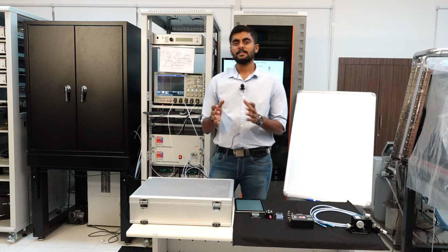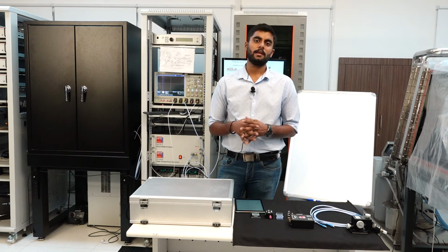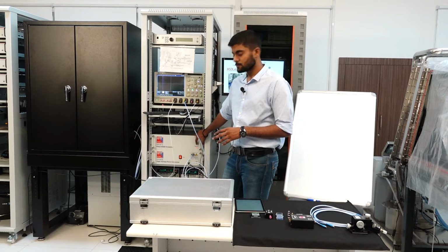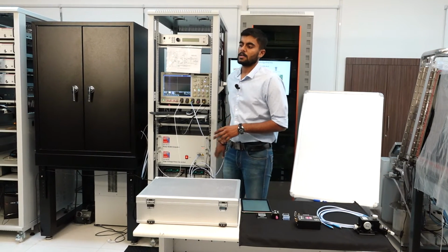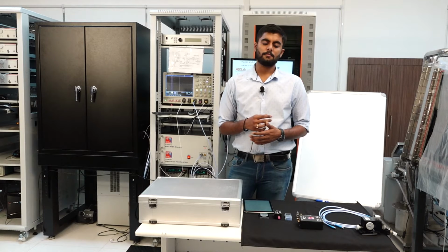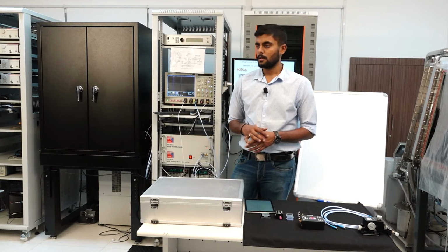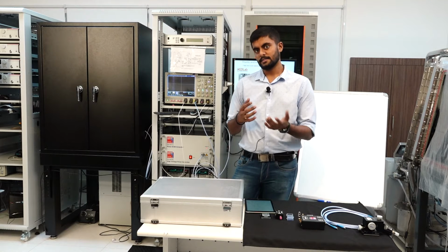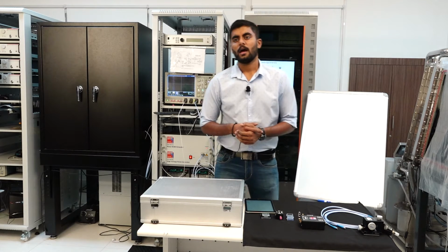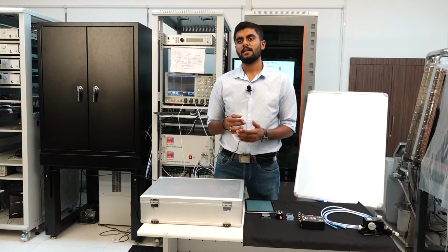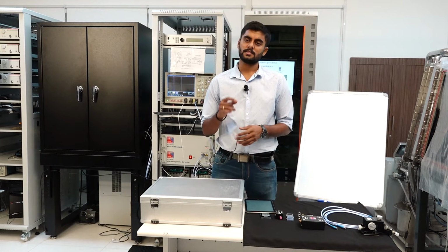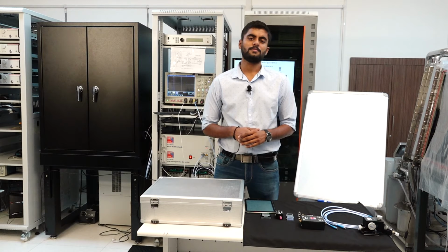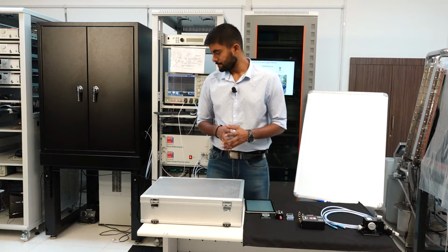So the first thing that I'll show you is what and how TLP pulses are generated. So this here setup, this here is a pulse width generator and extender. Now what is inside the generator is somewhat of an IP, so I would not give you too much information about it, but in a very basic way, it's an RC circuit, it's a transmission line, and you then charge these capacitors and transmission lines, and then whenever you want, you can discharge the transmission lines inside it, and you can apply the voltage waveforms and voltage amplitudes, whatever you want.